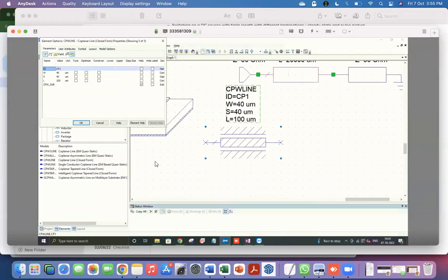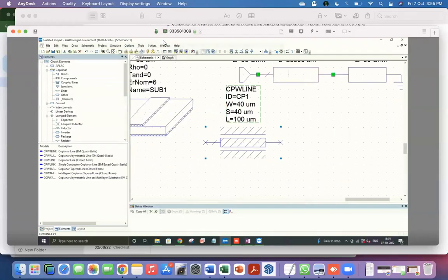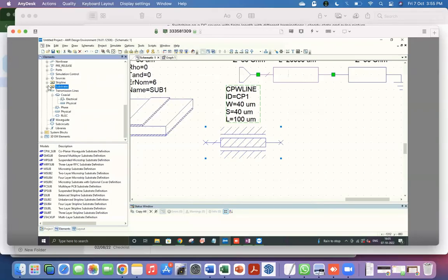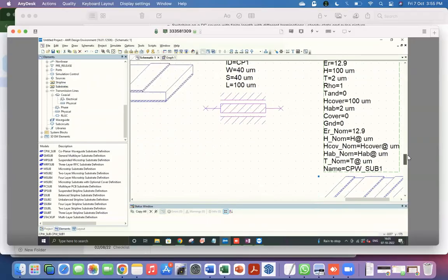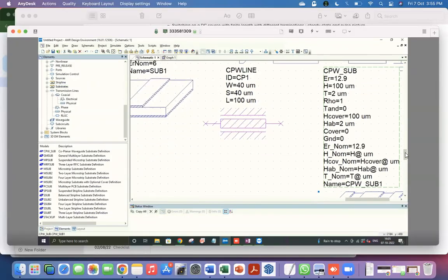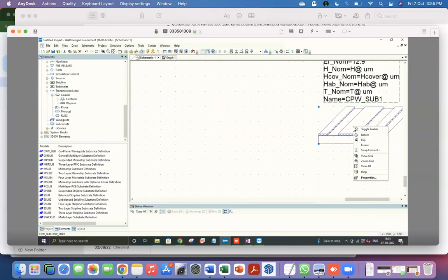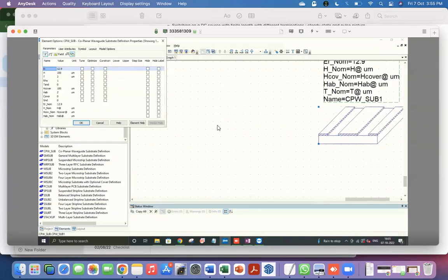it's not responsive now. So you go to substrates, and then you find the CPW sub here. It's right here, the top one. Okay. So since these are 2 different transmission lines, you can have them probably on the same structure. It doesn't matter. It has some huge number of different things, which you can check in the help file and see. Essentially, it should have the same dielectric constants, but there are probably some additional.